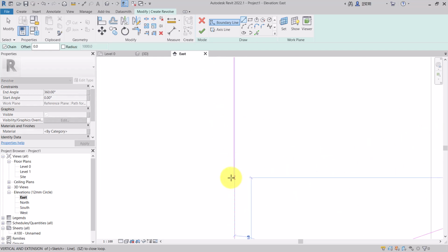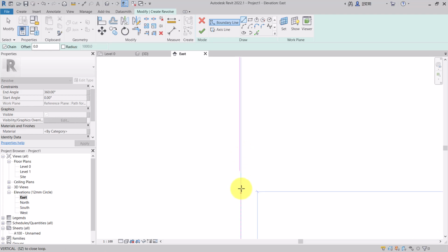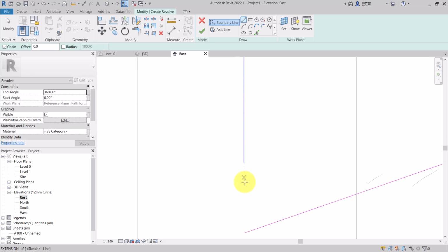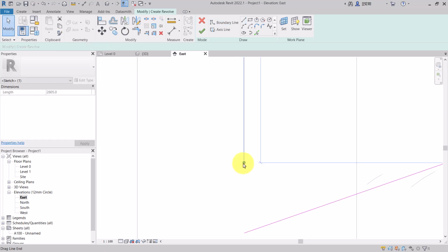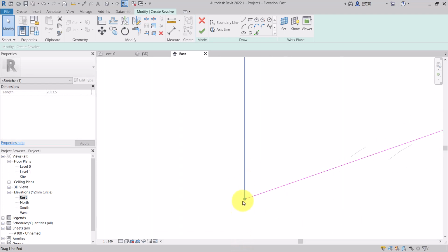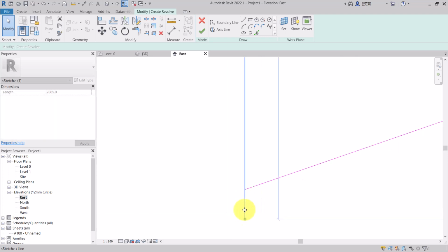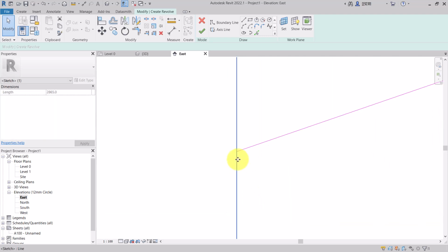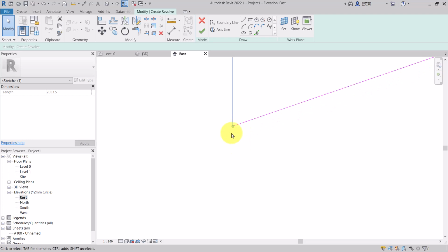It looks stubborn right now. It is, it's very stubborn. So we're going to drag this to the end. Hopefully it creates a boundary. If it doesn't, I'm going to have to zoom in manually to make sure that both ends actually meet. It shouldn't really be a problem, but you never know with Revit these days.